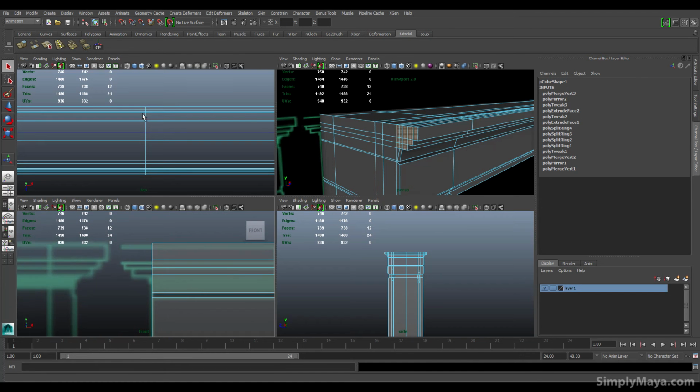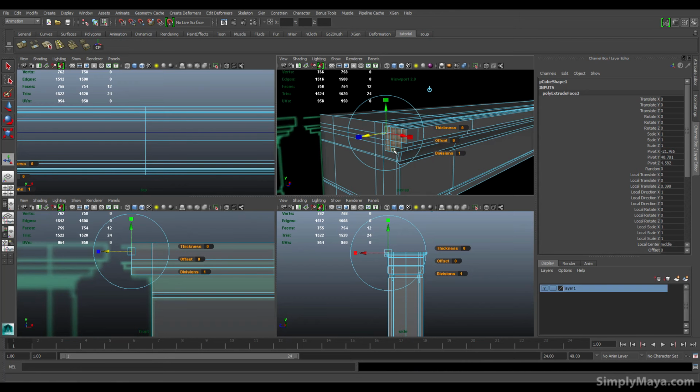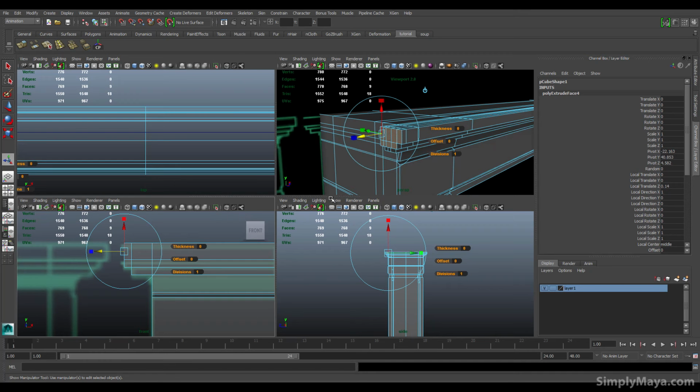And of course I'm just going to extrude these faces outwards now. So here we go, and I'm just going to extrude to the first point. Then I'm going to unselect these because we don't want to extrude them anymore, and then G to extrude again to the second point, and don't need that one anymore, and G, and out we go to sort of the end point.